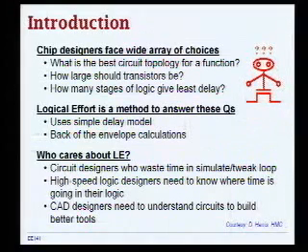This little chip guy is really confused, he's stuck the same way as we are now. He's dealing with very complex problems in his life. Gates, I don't know what to do with them. So now I have a lot of questions for a datapath. What's the best circuit topology for a function? How should I size these transistors? How many stages should I have for least delay? And I really have to make some important decisions. Luckily, logical effort is a method to answer all of these questions.